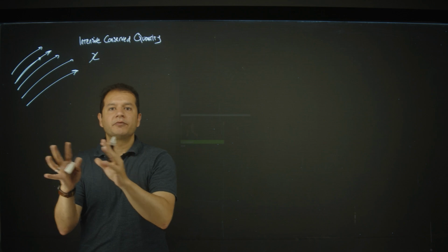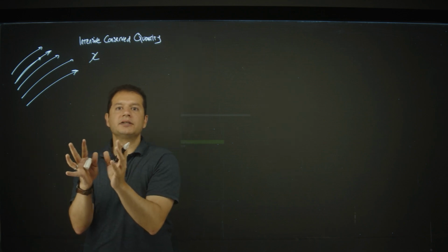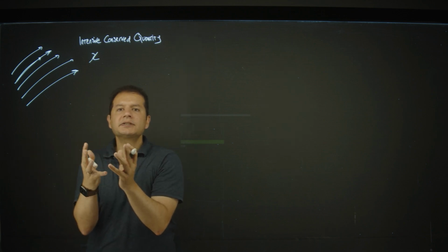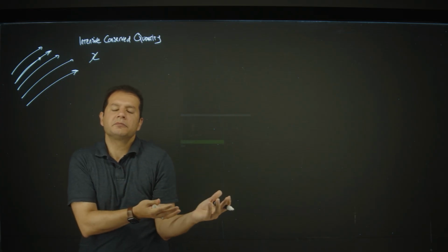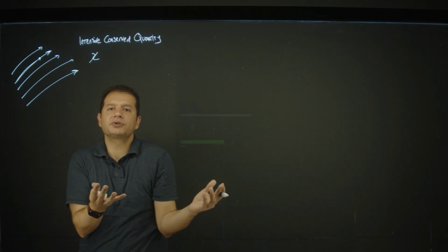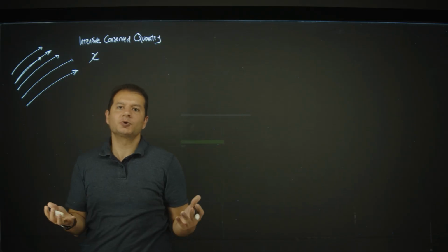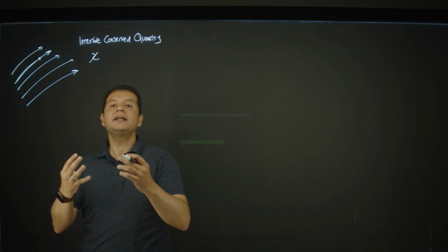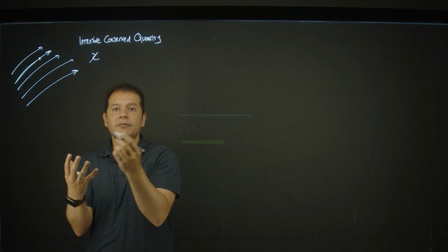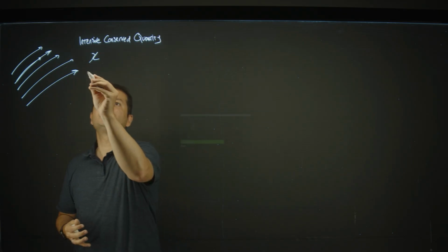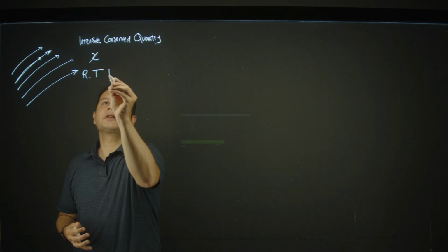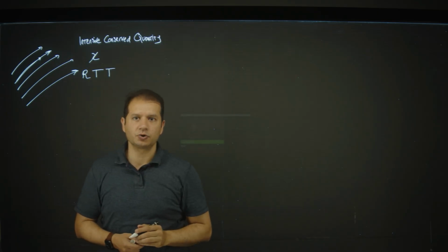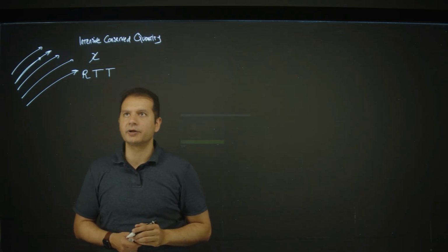There is a theorem for the transport of this conserved quantity, which says the change of the conserved quantity should balance the source term. If there is no source term for that quantity, it should not change. So we start with a theorem for the transport, which is called the Reynolds transport theorem, RTT in short.